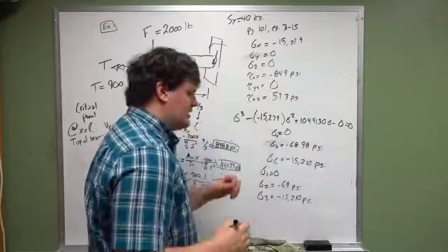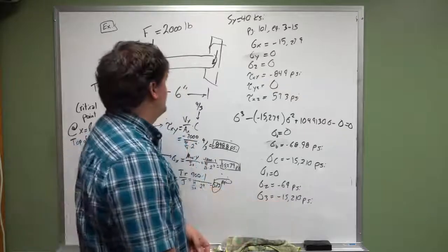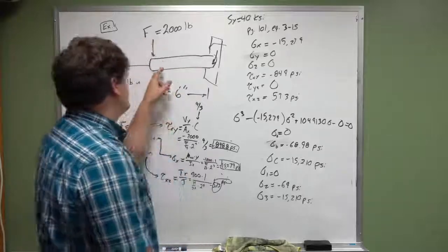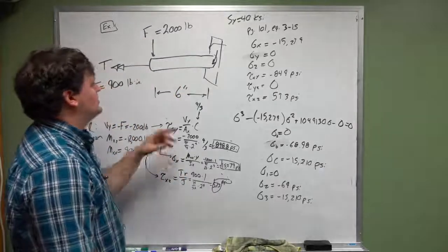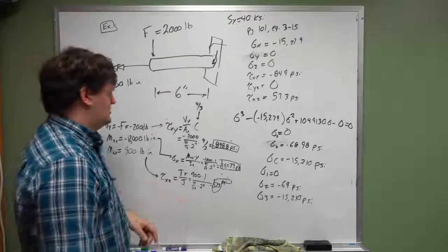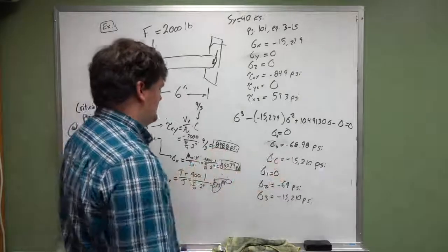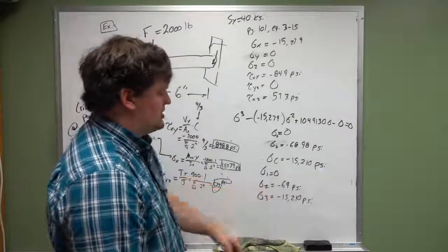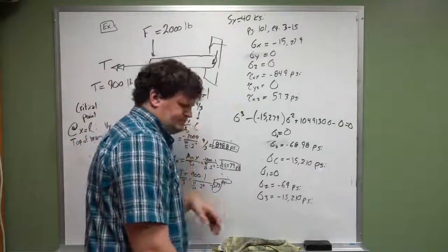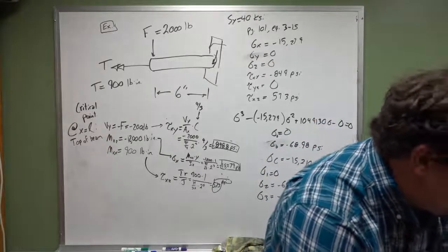Okay, I can go ahead and say, all right, this is in compression now. This is going to be very strongly in compression at the top of the beam. Had I done it at the bottom of the beam, no. It's actually going to be in tension at the top of the beam and in compression at the bottom. I should have used a negative Y value. But anyways, this is for the bottom of the beam because it's in compression. This could fail in compression. If you do it for the top of the beam, it would have been a different value.